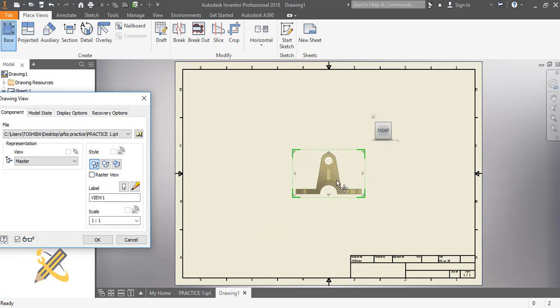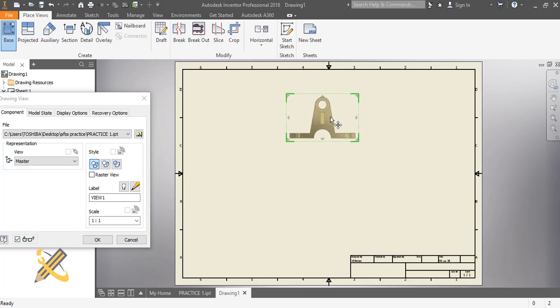So after having that here now, I'm going to decide to go for this particular view as my front view. So if I am producing this object in first angle orthographic projection, then in first angle, what comes first is my front view. Underneath my front view is my plan, and beside my front view towards the left hand side, I'm having the right hand view, and that is what I'm going to do now.